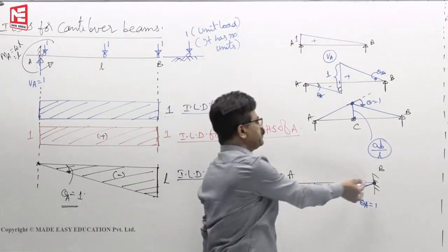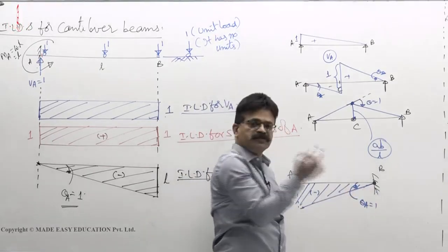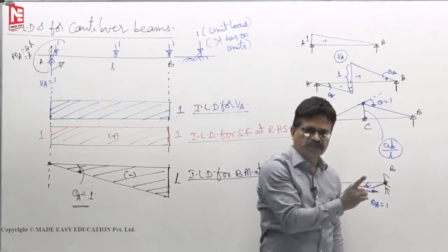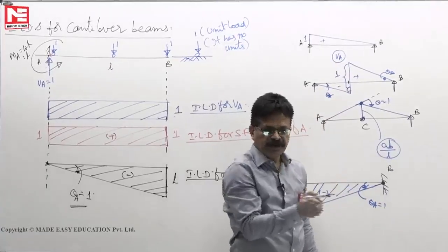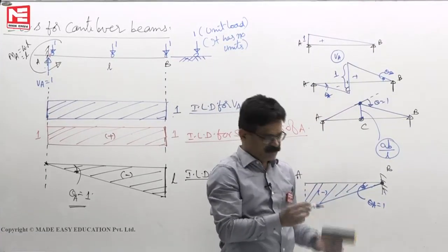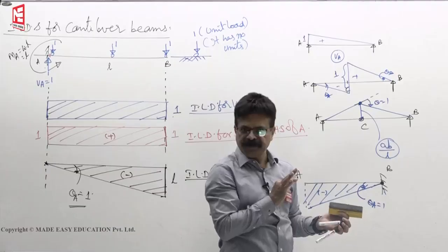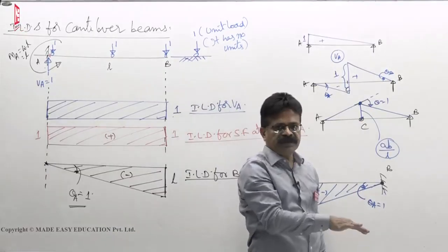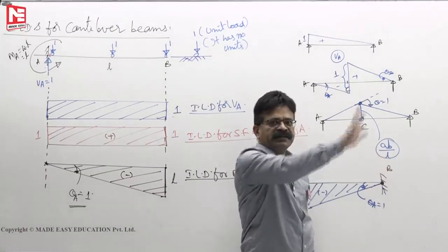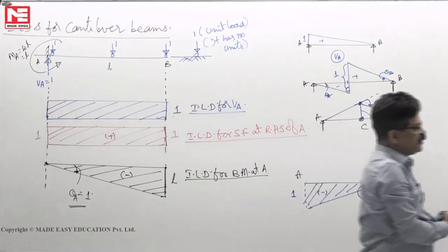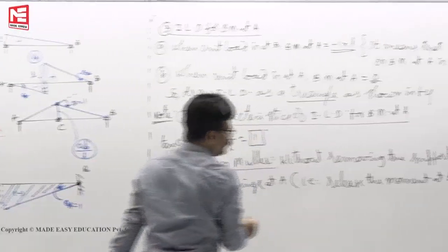To tell you that means from strength of materials, you must have an idea that due to downward load, cantilever beam produces hogging bending moment. In the cantilever beam, there will be hogging bending moment. So it should go down only. So either clockwise or anti-clockwise, let the beam go down this way. Release the moment at A and apply unit rotation.